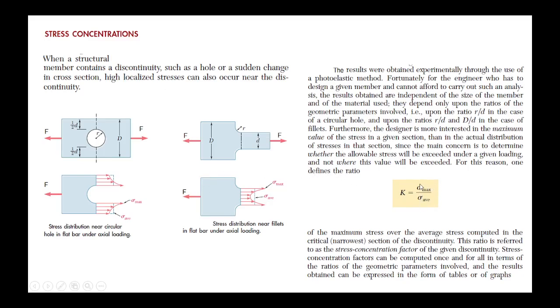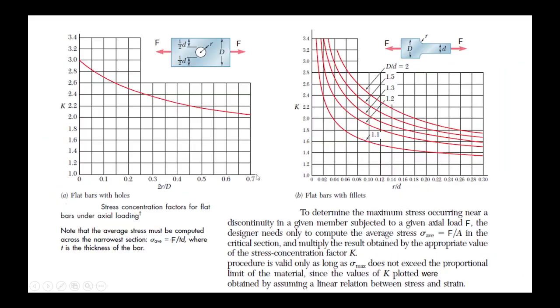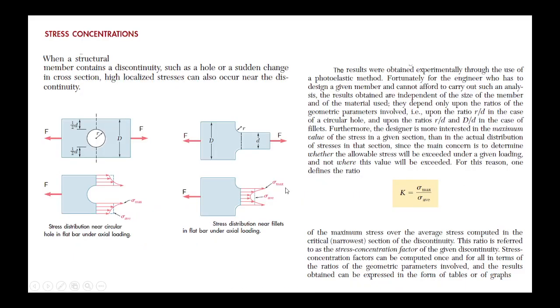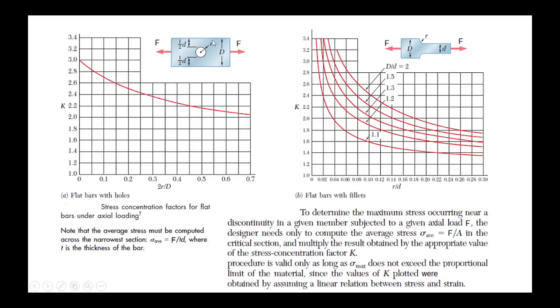The ratio between them is the stress concentration factor, and for such special cases we already have determined k factors, given in the publication in the literature. It is available, and this publication is also covered in strength of materials books. Okay, to be able to study the example, obey the recommendation.